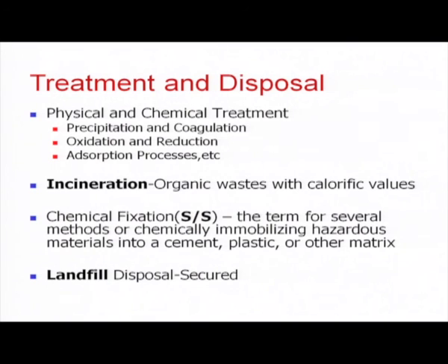So, to sum up, hazardous waste is one of the important topics of environmental management. First, we should know what hazardous waste is and what its properties are, the four properties: corrosivity, reactivity, ignitability and toxicity. We have to check and ensure whether it is hazardous or not. Also, there are rules on whether it is a listed waste in the country.